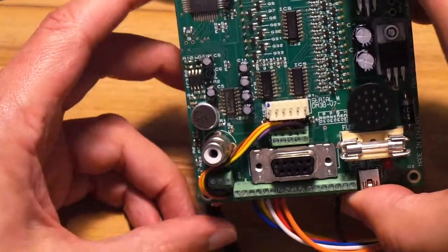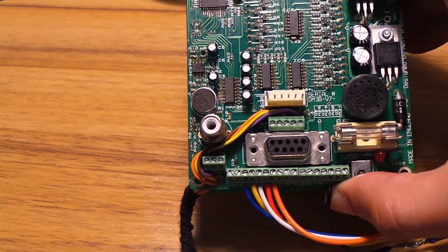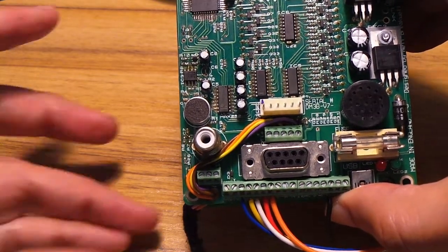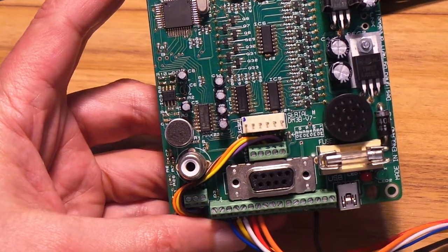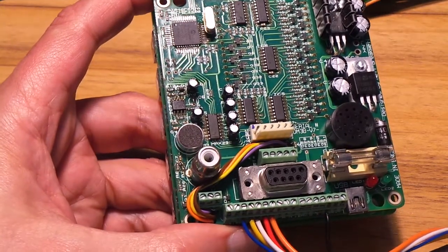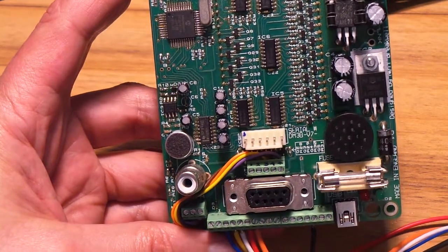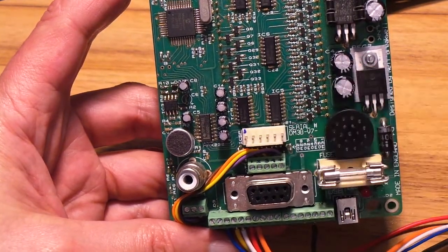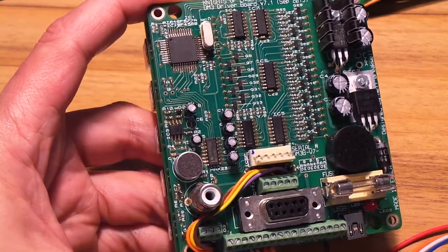The pin that goes to the common will need to be branched off to all of the indicators on the high side, and then the individual other connections on pins 1 through 4 will go to the ground connection of the individual dash-top indicators. We also have this 6-way in-circuit serial programming port for reprogramming the module.